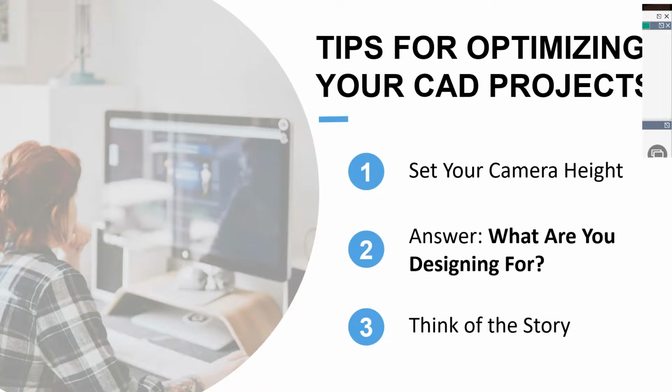Okay, so now let's go over some key tips for optimizing your CAD projects for VR. In your CAD program, like I said earlier, set the camera height to 5'6", regardless of if you're doing 360 photography or designing in CAD. This can be important because dropping someone into a scene at the wrong height can actually be a little bit nauseating and kind of disorienting. The 5'6" camera height will give you a good perspective height when you're viewing the VR project.